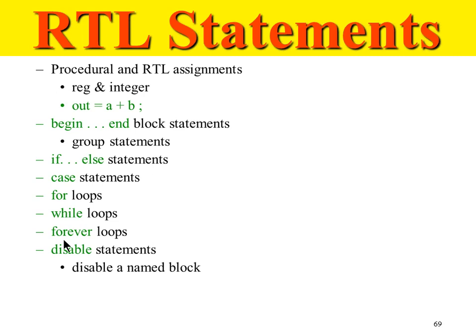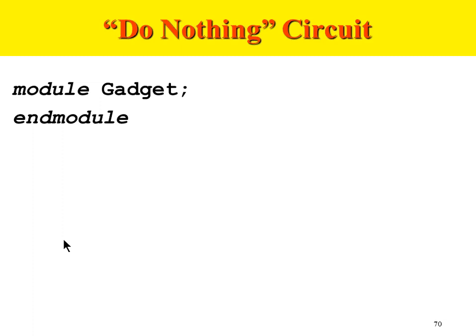And disable statements, we can disable a statement, which is also something fancy, which is not part of the design. It is not synthesizable. It can be used for test bench purpose, but not for the design part of it. Let's look at some example.